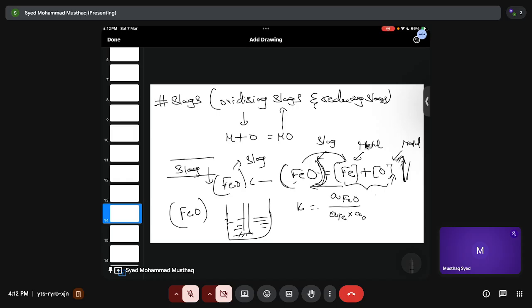Because of this oxygen, carbon, an impurity, will form carbon monoxide because of the temperature, and it will go into the slag and form emulsion. In slag, you will have FeO and also carbon monoxide, and this carbon monoxide will reduce your FeO, and that Fe will trickle down through those bubbles to your melt.